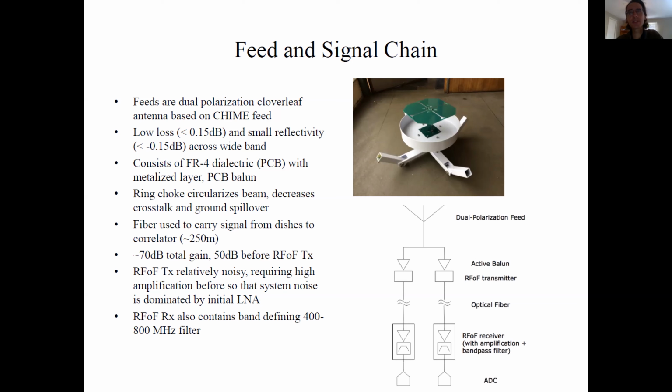So it's my understanding that it's not the dynamic range, but it's that the step where you're modulating the RF into optical so that you can transmit it on laser, that's just noisy. This is something that's been developed kind of in the field. A lot of the other technology on these radio telescopes are just kind of hijacked from the commercial world, because they've developed wonderful amplifiers and things for cell phones and everything else. But this is not something that's been developed elsewhere. So it's very new. So it's possible that it will become less noisy in the future, but it is not right now.